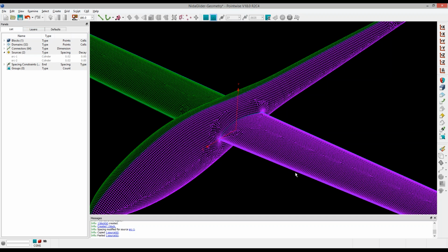It comes down to the way T-Rex is going to be advancing elements off of the surface. T-Rex is anisotropic tetrahedral extrusion. It's a tet meshing algorithm that advances right-angle tets off of the surface, and then after the fact it combines them. It does that because you get more flexibility, it's more robust, and all the faces are triangular. And then in the end, it'll combine all of those into hexes, prisms, and pyramids, and then have tets in the far field. The thing is, when you give it a quad mesh, we need to somehow expose triangles.